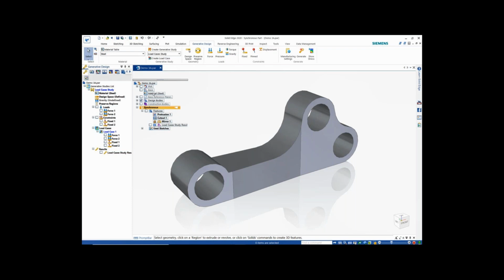We've got the generative design pane open, and the generative design tab is active. You can obviously see the improved colorization in your study to help you just visualize all your inputs. Now this has already been done. So you see that here's one force pointing upward, and then there's another one pointing downward. So it's a little hard for the software to generate the most optimal design when they're kind of combined into that one load case. So that's why they've added the ability to make separate load cases.